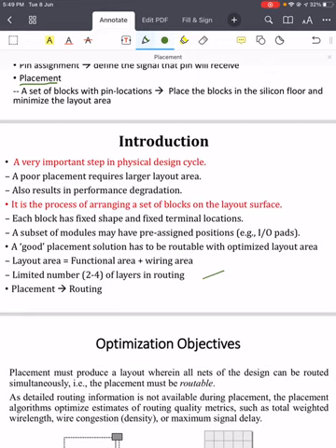This is the inherent limitation of routing, that is, the limited number of layers, and because of that, some placement solutions may be unroutable. Okay, and such a placement solution is usually called a bad placement solution, which is unroutable. However, the fact that a given placement is unroutable will not be discovered until routing is attempted. And this leads to very costly delays in the completion of the design. Therefore, it is very important to accurately determine the routing areas in the chip level placement problem. Okay.